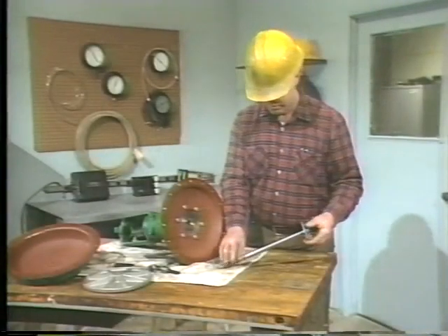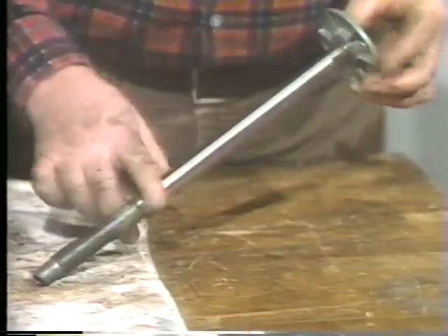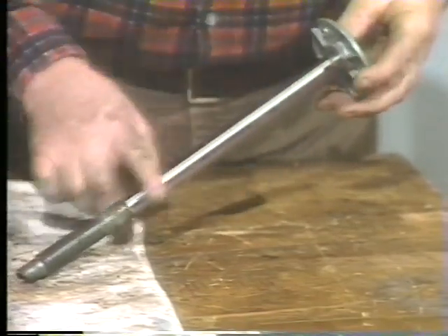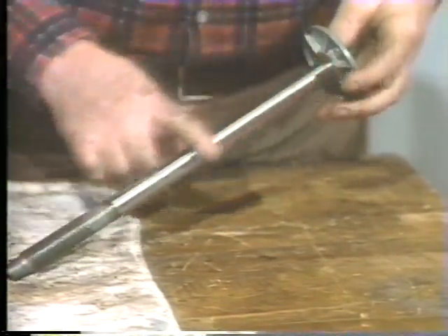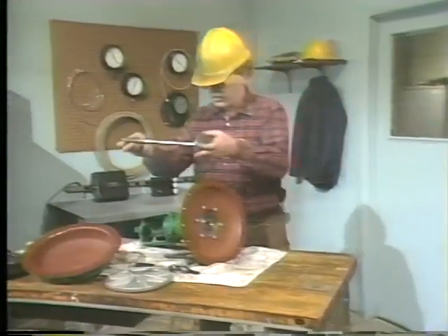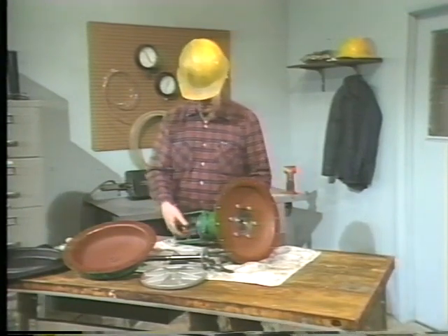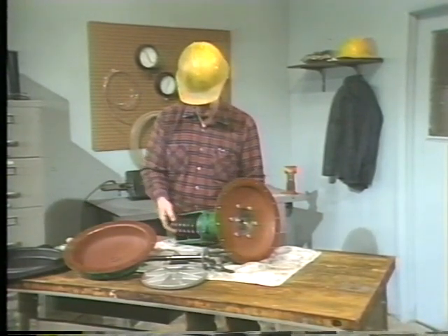The last part of the diaphragm and stem assembly is the actuator stem. The stem is continuously subjected to wear and stress as the actuator converts air pressure into motion. Sometimes this stress is severe enough to bend or break the actuator stem. Of course, when this happens, the stem would have to be replaced.